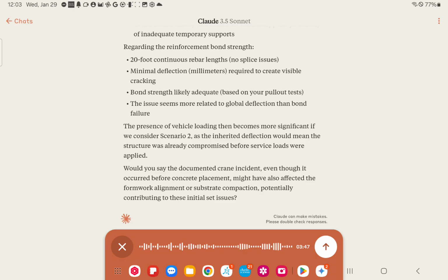The pool deck has the concrete deck over top of the columns, giving you more resistance to punching, whereas the pool deck by the parking garage area with the columns going up with the higher PSI terminates around the column, if you will. It does create a cold joint, whereas the others do not create a cold joint.